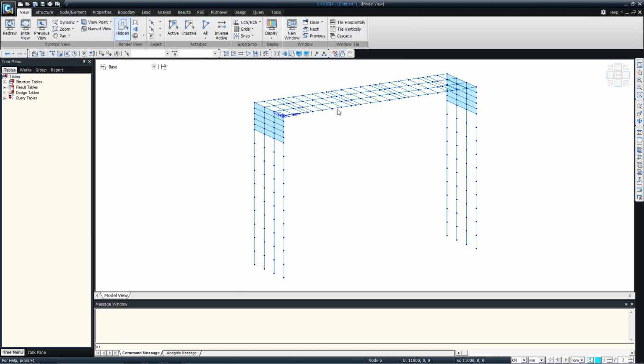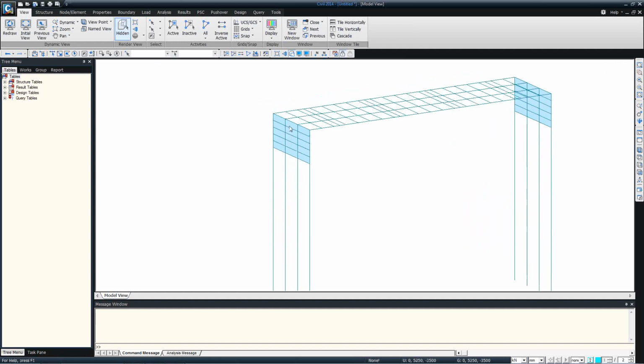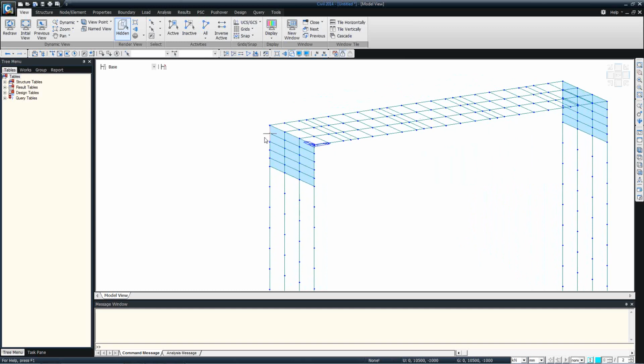So all these beam elements which comprise the composite steel girders, they should be modeled as lines. So nothing should be polyline in AutoCAD. And then you have the piles. Again, they should be lines with all the required intersection points already made in AutoCAD. And these shell elements which represent the abutments, they should be 2D or 3D face elements in AutoCAD. So if these parameters match and the unit system matches, then you should have absolutely no problem in importing the model from AutoCAD. So that's how you import the model from AutoCAD.